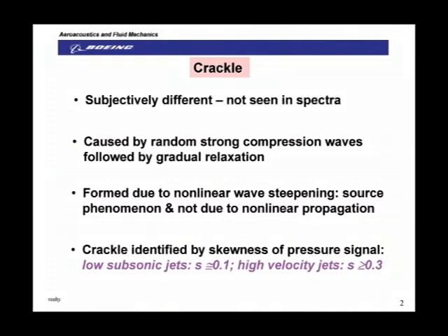Now, Professor Ffowcs Williams and his group noted that crackle was already present in the near vicinity of the jet and proposed that the origin of the crackle was due to nonlinear steepening at the source, which is not directly connected to nonlinear wave steepening due to propagation over very long distances. Thus, crackle and nonlinear wave propagation are two distinct phenomena, though they share some common characteristics.